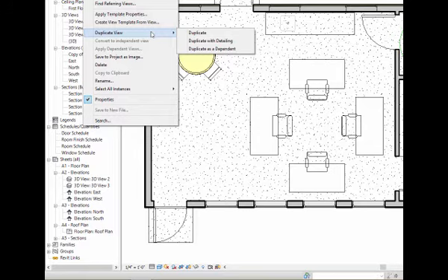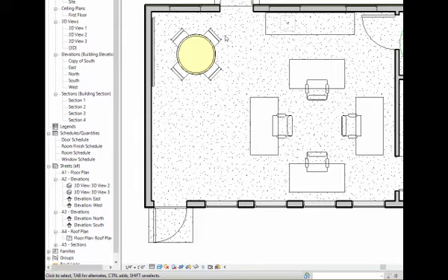And you'll see there's a couple choices there. I can duplicate either just the model objects. If I choose that first choice, that's just the model objects. If I choose the second choice, that'll actually duplicate the detailing. That means if there's any dimensions or annotations, include them too. So let me just try duplicating it first, since there's no annotations on this one. Show you that it actually creates something incredibly similar. It's just a copy of the first floor view.